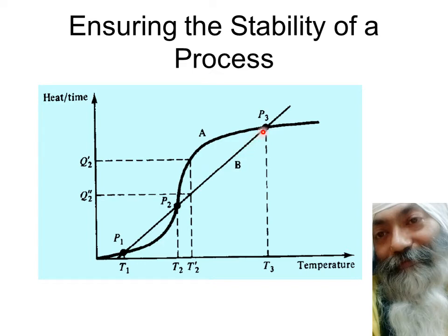So as the temperature becomes higher and higher, the difference becomes higher. And as per Newton's law of cooling, if you remember, the amount of heat extracted is directly proportional to temperature for a given flow rate. I'm repeating again and again, because if I change the flow rate, then the slope of this may also change, and I don't want to discuss that at this moment. So I'm keeping the flow rate of the coolant fixed.